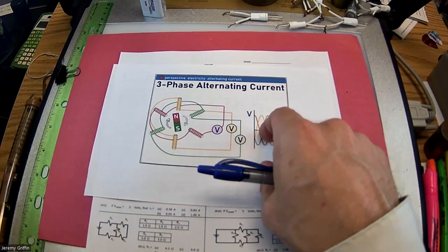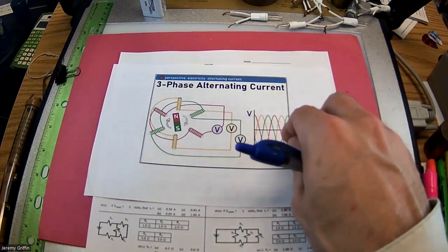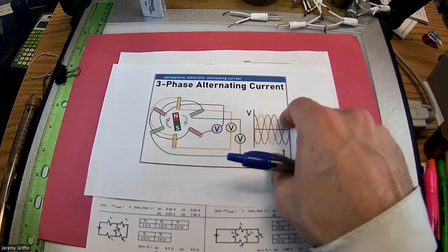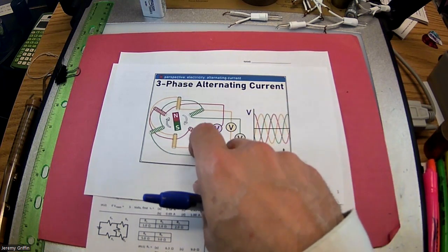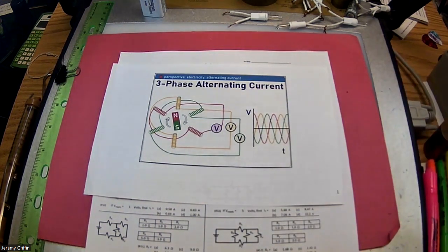So it would be like your electricity would be turning off. Okay, well, if we had more phases, then we can kind of negate that effect, make it more constant, sort of, right? But then the trade-off with having more and more phases is that's more and more materials to build it. So the trade-off is they went ahead and went with three.